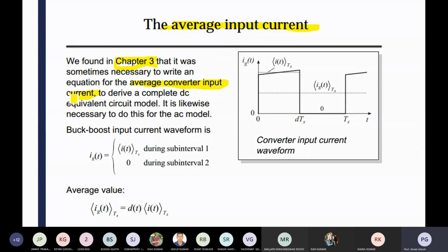In a normal boost converter, the inductor current is the same as the input current, so you observe the same ripple content in the input current. There is no option for current ripple cancellation. But if you connect the boost converters in interleaved mode, then when one switch is off, another switch is on. It counters the off-time current ripple, so we get a vector addition of the three inductor currents.